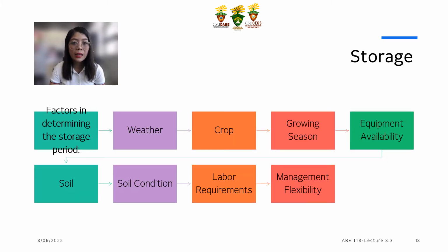So now let's proceed to storage. For storage, our waste must be stored so that it can be used when the weather condition is appropriate, and kept when the weather is inappropriate. Storage facilities for waste of all consistencies must be designed to meet the requirements of a given enterprise. We should anticipate whether the waste will be liquid, slurry, or solid, and provide storage facilities for all consistencies of waste produced.